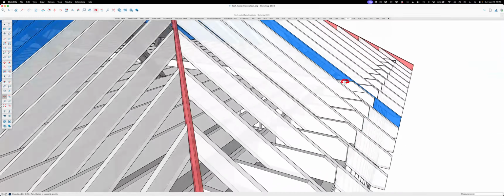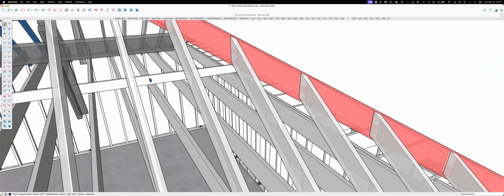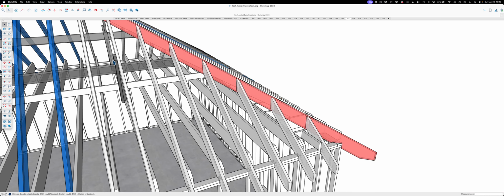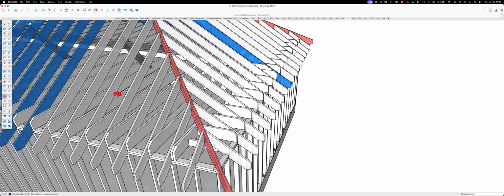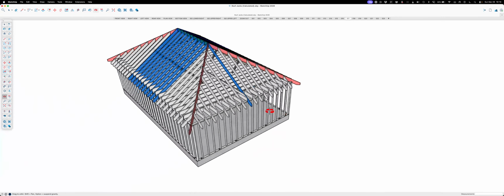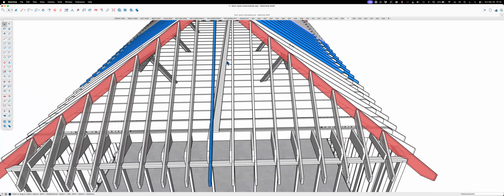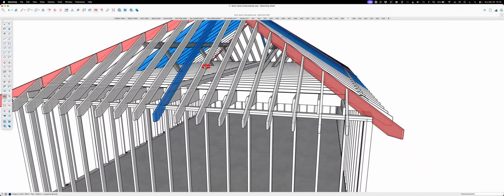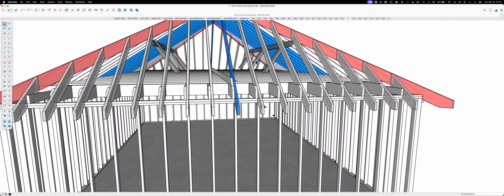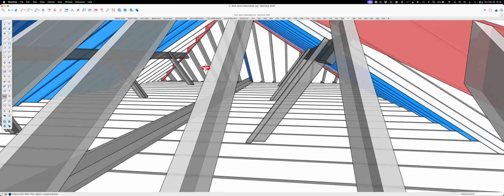Now I have done where the stiff back doesn't go all the way through, and wherever I needed purlins, we ran bigger joists, like make a beam out of it. But that's something that an engineer or an architect will let you know if that's copacetic. But that's how, and let me just show you how.